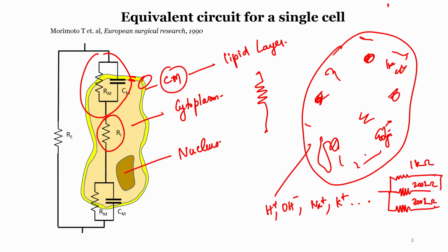Okay. Now what is the effective resistance? Let us say we simplify it, we are just connecting a very high resistance and a low resistance. Now here this low resistance is the ions, because ions, as you know, are quite conductive, right? So they will have very little resistance. Let us say this 200 kilo ohm is from the organelles, because they contain lipids and proteins and all, they are heavy molecules and they will have high resistance. Now what will be the effective resistance of this parallel combination?